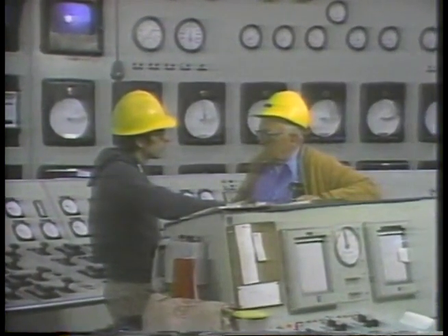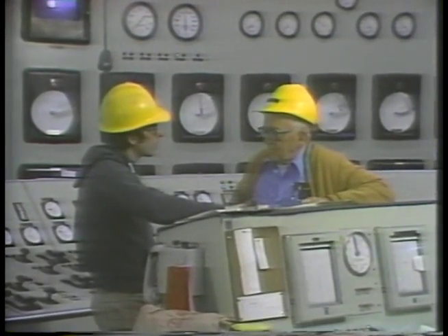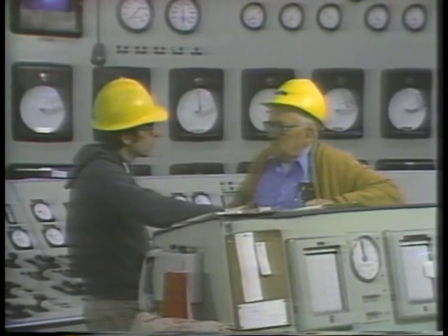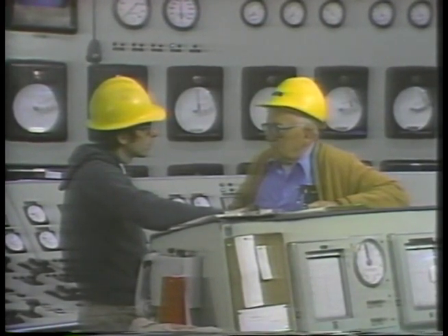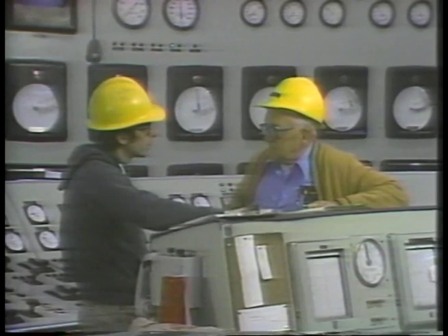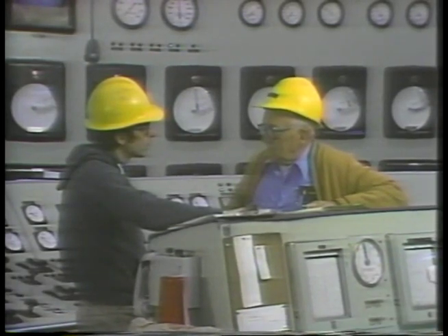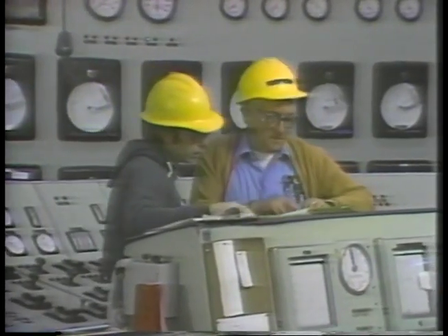Discharge pressure on the mills, make sure you don't load up any mills and trip them out. I heard you guys had a problem with number 2 fuel oil tank. Yeah, we were going to pump the oil out of it, and the automatic vent valve was corroding shut. So it didn't open up, and we pulled a vacuum on the tank, collapsed the sides in on it. Quite a bit of repair work there to do. Did somebody take out that pump? Well, I don't know. It should be in the logbook. Let's see here. Yeah, Mary tagged it out.